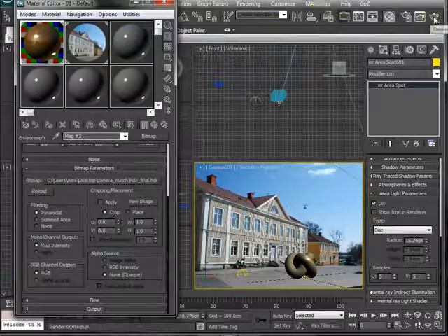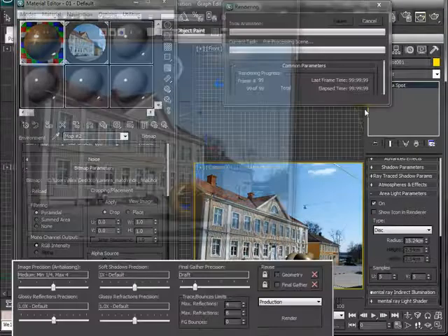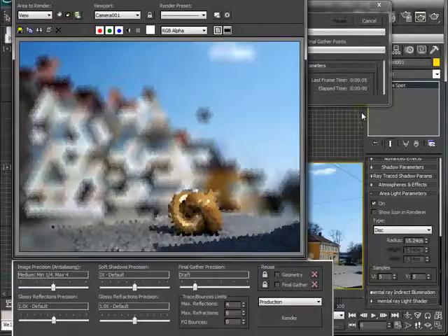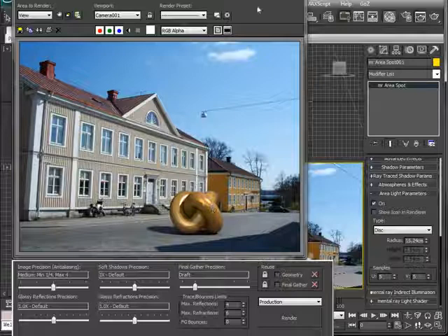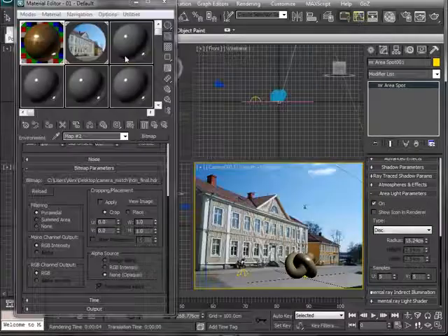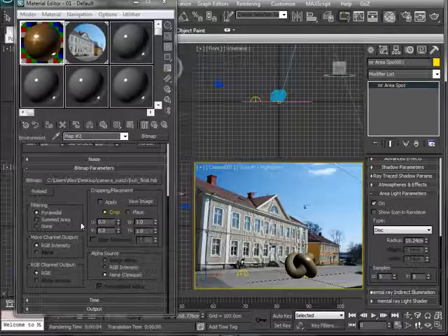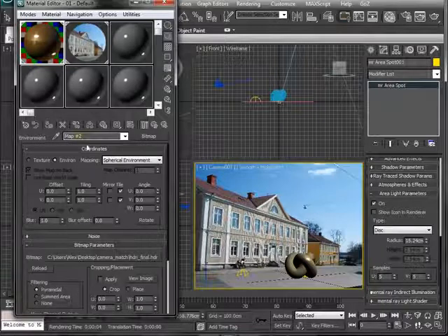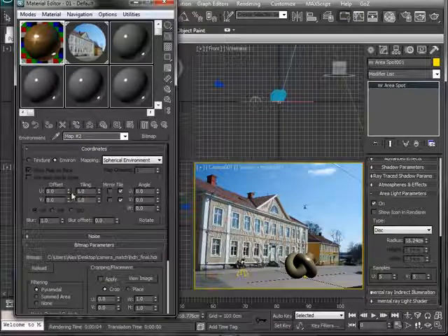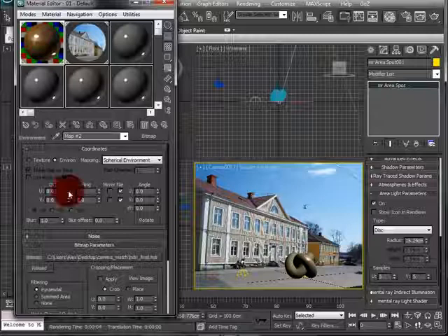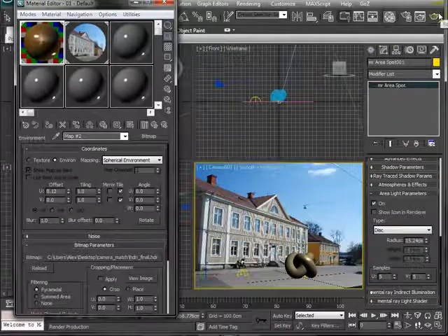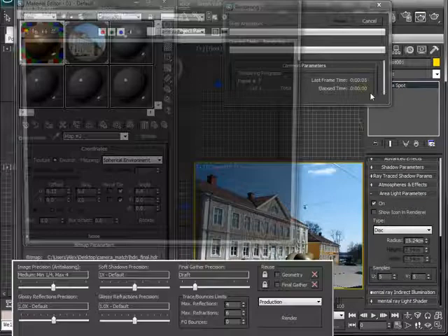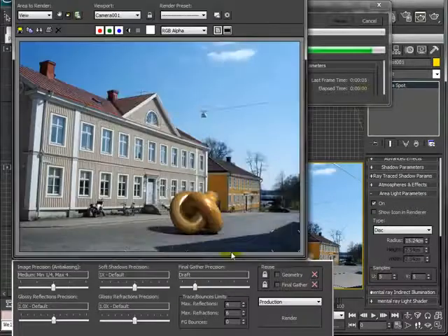But if we have a quick look, excellent, you can see that now we've got a bit of reflection in there as well, this hot spot from the light. If you want to move how that texture is set out, in the texture tab you can start playing with the offset of that texture and do another quick render to see how that's moved the light spots for us, which will do nicely.